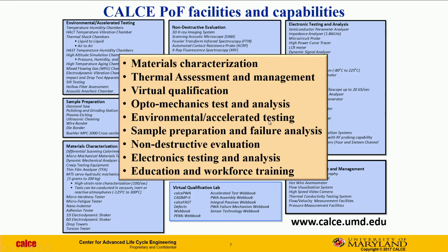Environmental and accelerated testing, a lot of my own work is done here. We still do a lot of environmental testing because the design tools that we are building have to be verified, have to be validated, and model constants have to be calibrated. So we do a lot of accelerated stress testing: thermal cycling, power cycling, temperature, humidity, bias, shock, drop, vibration, you name it, we do various kinds of tests. I'll talk more about that later on. Some of our test labs are geared just towards that.